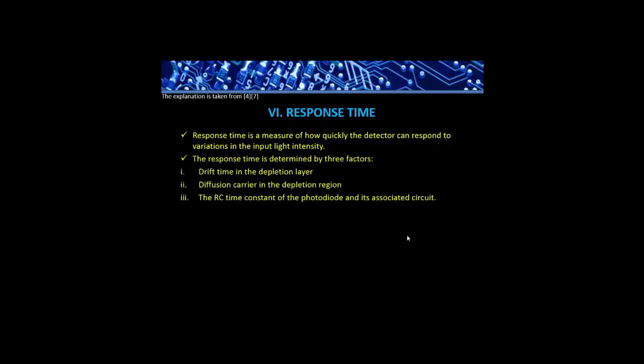Response time is a measure of how quickly the detector can respond to variations in the input light intensity. The response time is determined by three factors, which are drift time in the depletion layer, diffusion of carriers in the depletion region, and the RC time constant of the photodiode and its associated circuit.